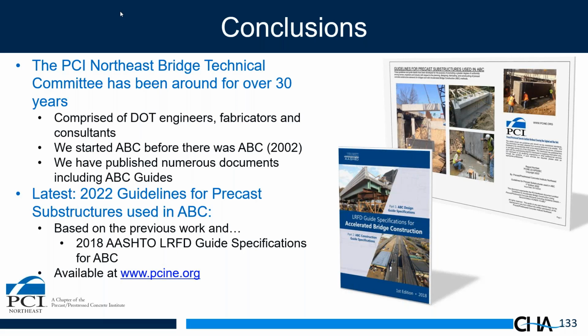If I have a pier cap that weighs 1,000,000 pounds, some of these pier caps weigh 1,000,000 pounds, I have to build formwork at elevation to support 1,000,000 pounds of wet concrete. I have workers working at elevation with fall protection up in the air. So very expensive forming, very expensive labor to get this thing done. Precast, I set the piece in 15 minutes and I'm out of there.